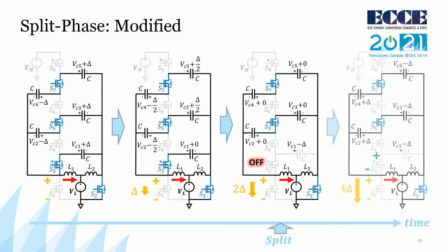After this time, we see that S3 incurs a positive forward voltage bias, removing the possibility of any reverse conduction and allowing our fly capacitor voltage ripple to be greatly increased. Dissimilar to the previous method, where the splitting event could be actively sensed by the bias across S3 going to 0 volts, here we must rely on calculated timing durations or indirect measurements, as any timing errors here won't incur hard charging effects until the start of the next phase.